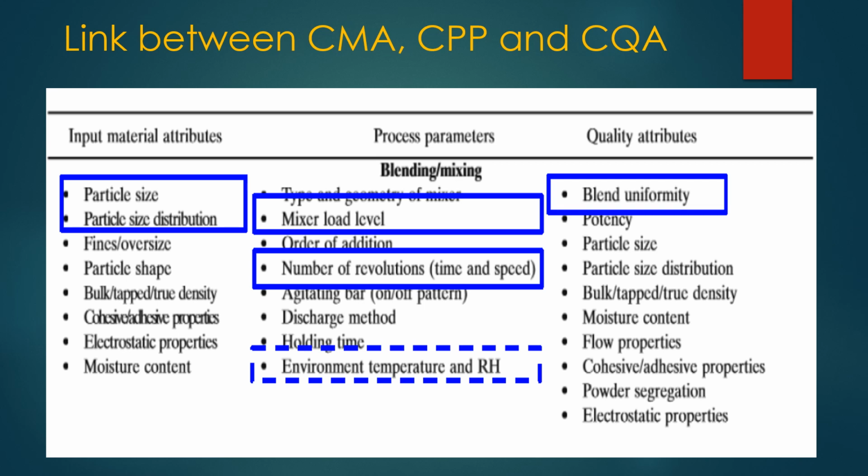Right attribute materials may reduce the variability in unit operation, and operation can be well controlled by applying critical process parameters. Let's understand the impact of departure from the input material attributes and process parameters. Variation in particle size and size distribution can potentially affect a product's manufacturability, efficacy, quality, bioavailability, and shelf life. Particularly in API, it may potentially impact blend uniformity. This can be a high risk for other CQAs like content uniformity and assay.